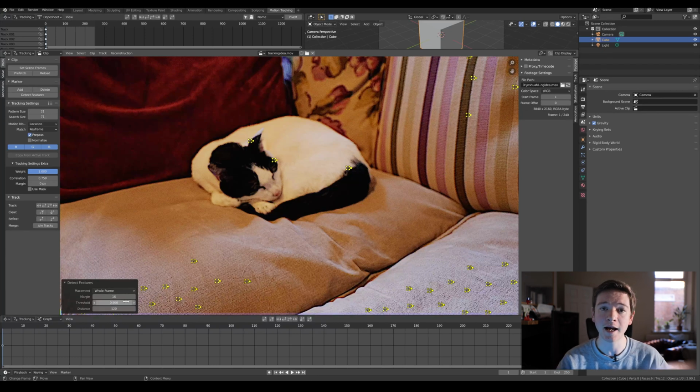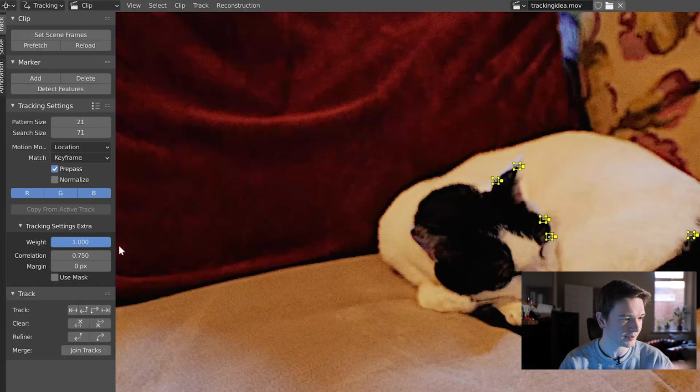And now we actually have some tracking markers. For this footage, I'm going to set the distance to be lower. This is the distance between tracking points that is allowed. Currently 120 pixels. They will always be a minimum of 120 pixels apart. I'm going to set that to 60. And now we get a lot more trackers down the bottom and on brisket.